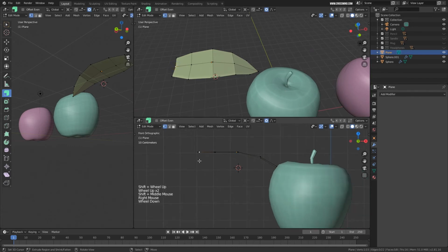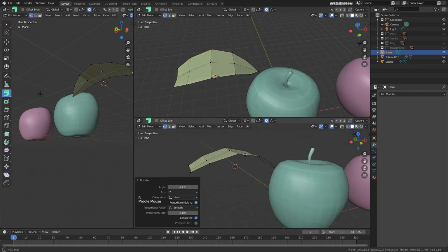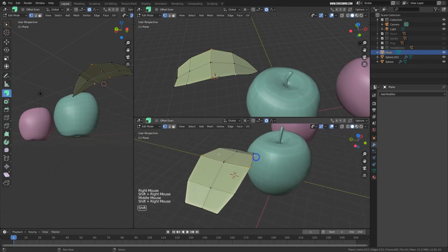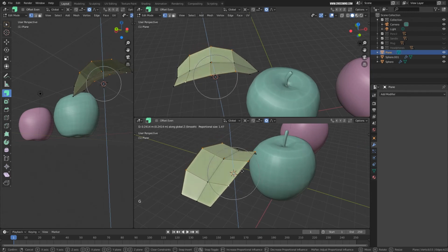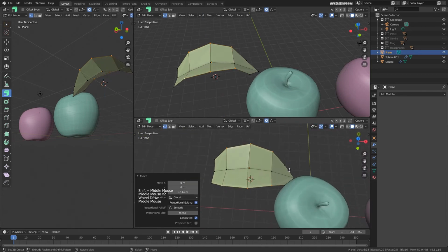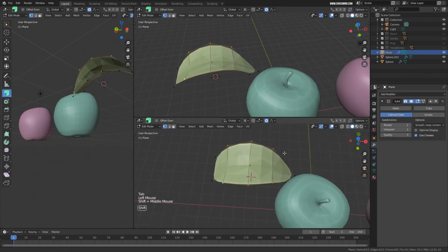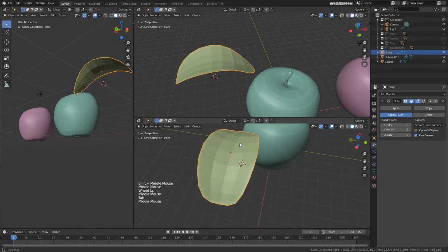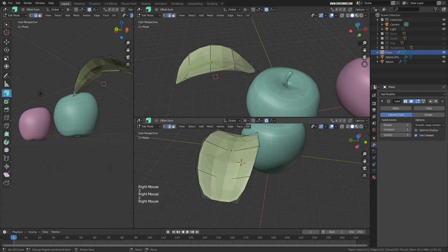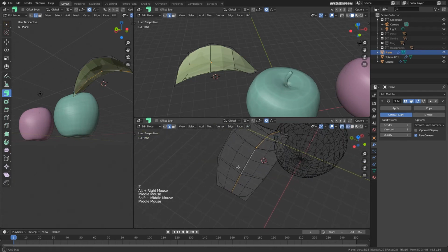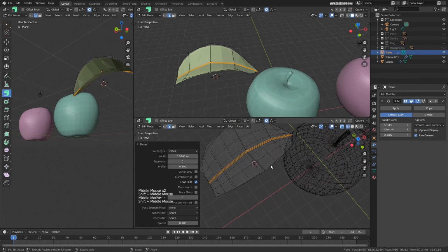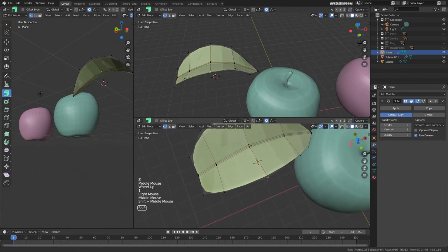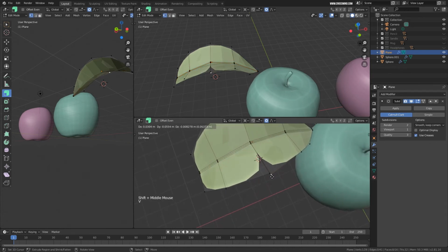Okay, now I'll select this side and I'll rotate this one like this, and I can select these two sides, these 6 edges, and move them up like this. I'll reduce the size of proportionate editing and move them up like this, and let's apply one subdivision surface over here, and we need some hard looking edge over here. I'll select this entire edge loop, press Ctrl B and give it some bevel, and maybe if you want to stylize this one, you can press V and break this one.